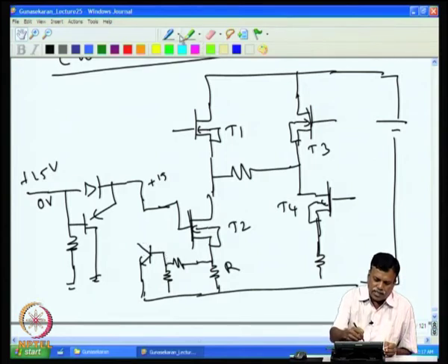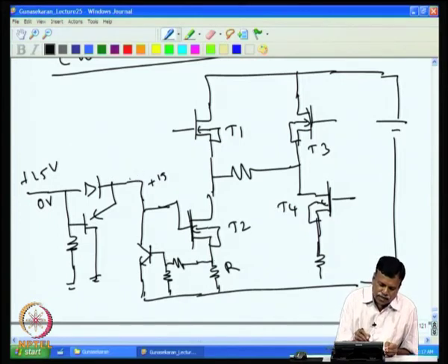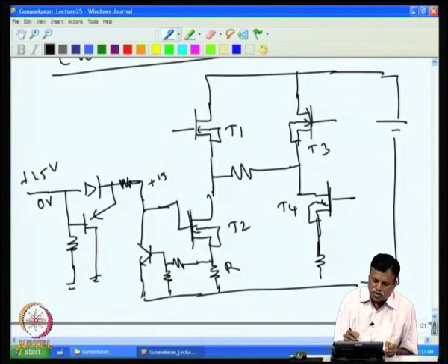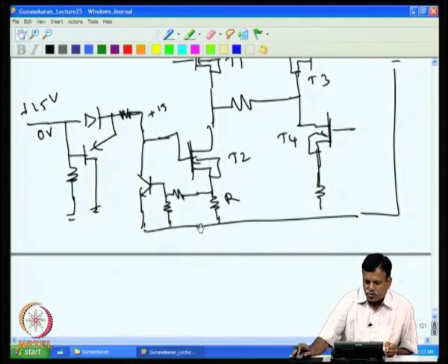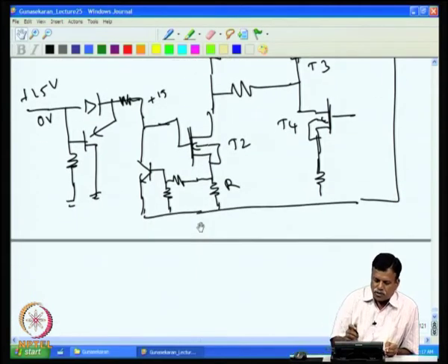So, I can connect this here, but if I connect like this, the problem is that this will be limited to 0.6 and the conduction will take place. Assume that I have a small resistance here. So, the voltage drops such that always 0.6 is at this point, and then this transistor T2 will be taken to a linear region. This is a conventional linear regulator current limiter.